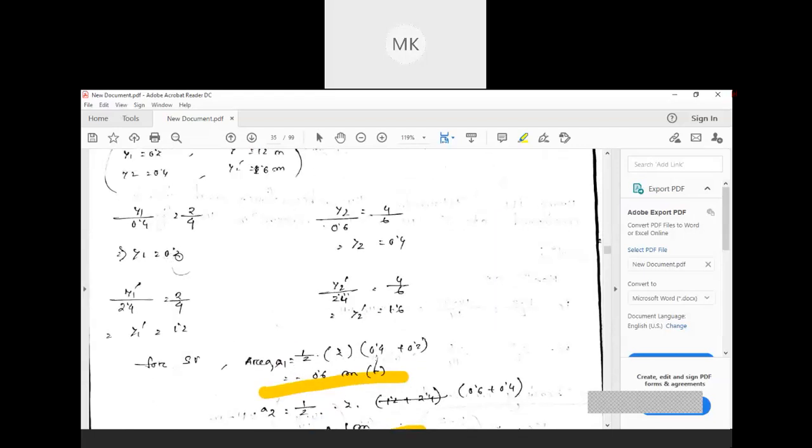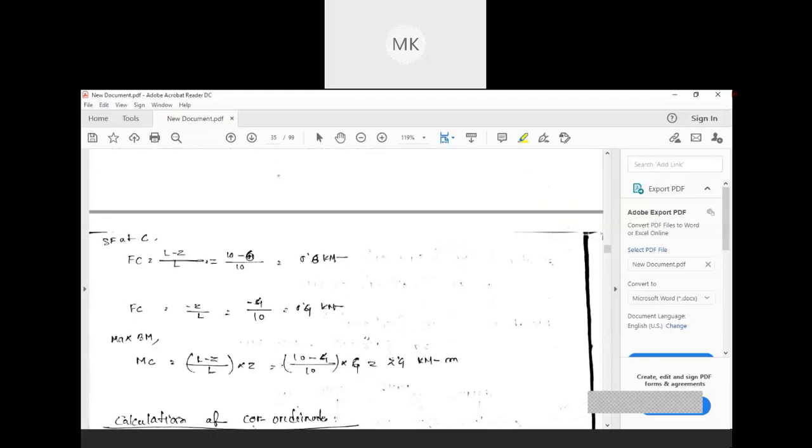And again the same thing will come, because we are considering this ordinate. But when we did it earlier, considering dead load, we were not supposed to find this ordinate. We were simply following the basic steps, taking out the reactions and multiplying, to find the shear force and bending moment at a particular point. But this time, for moving load, for finding the ILD, we need to follow this pattern.